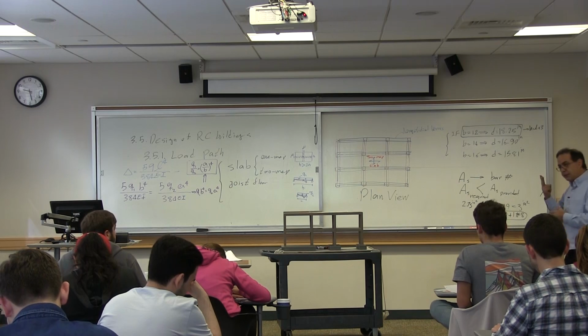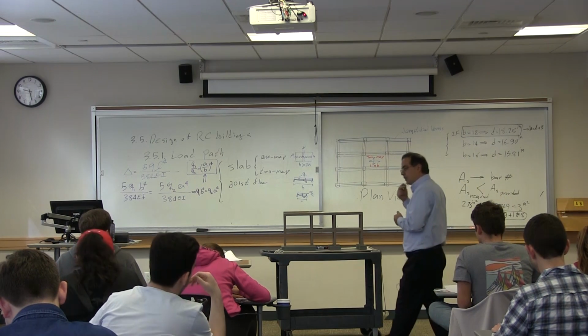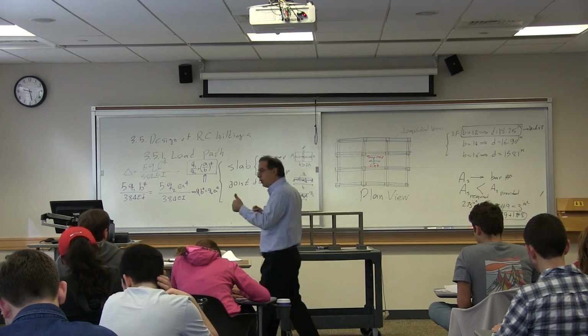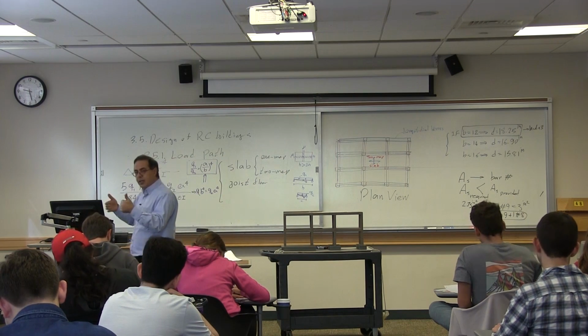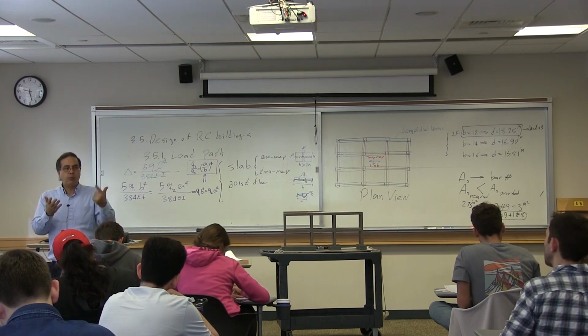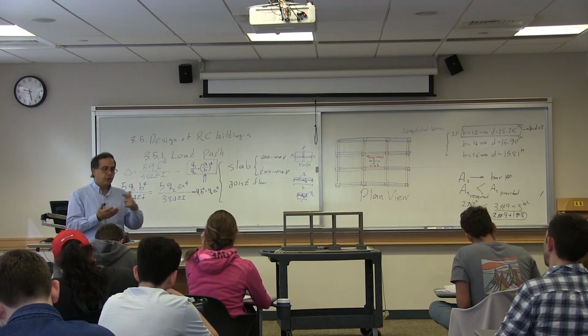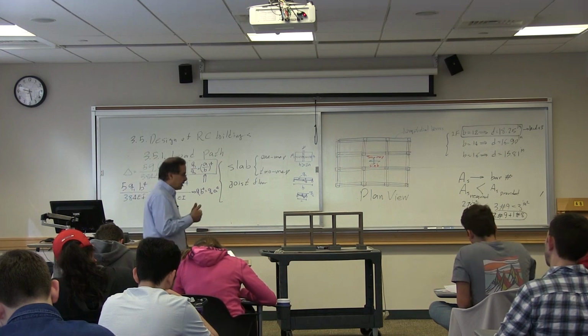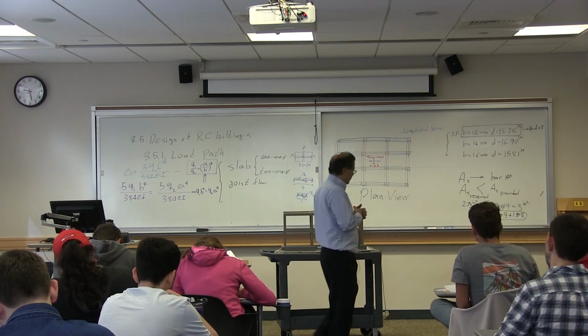Okay, so therefore, because of these two reasons, you want to design the floor system first. One, load path, that means which direction the loads go. Two, how much is the load. Because of those two reasons, first you decide on the floor system.